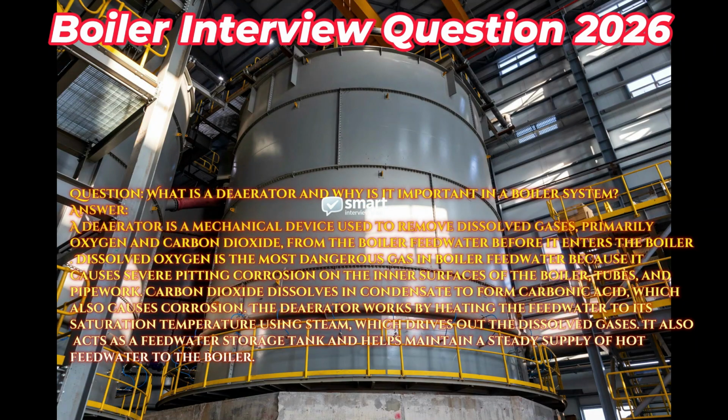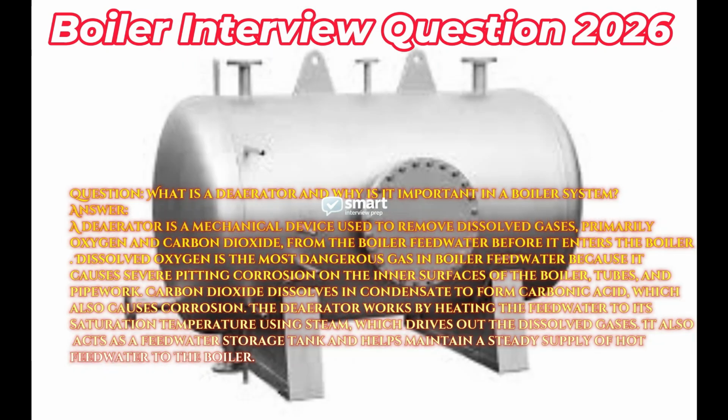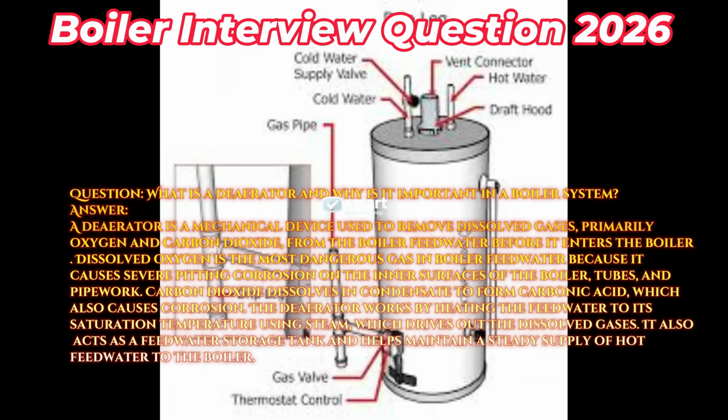Carbon dioxide dissolves in condensate to form carbonic acid, which also causes corrosion. The deaerator works by heating the feedwater to its saturation temperature using steam, which drives out the dissolved gases. It also acts as a feedwater storage tank and helps maintain a steady supply of hot feedwater to the boiler.